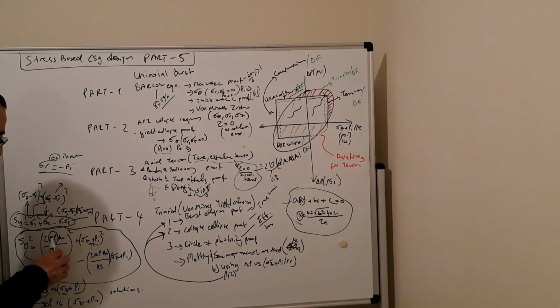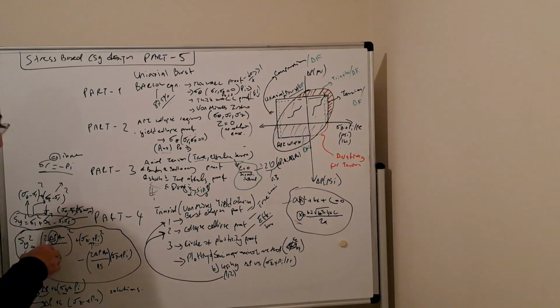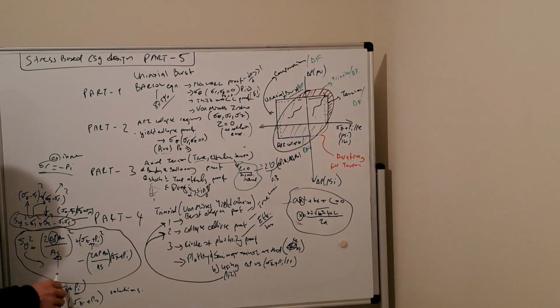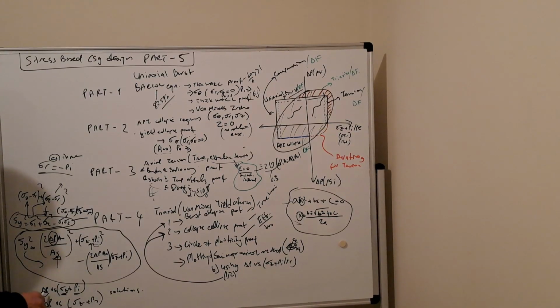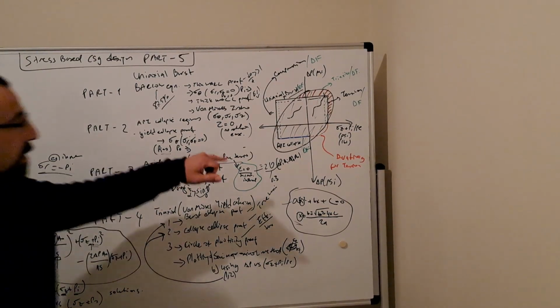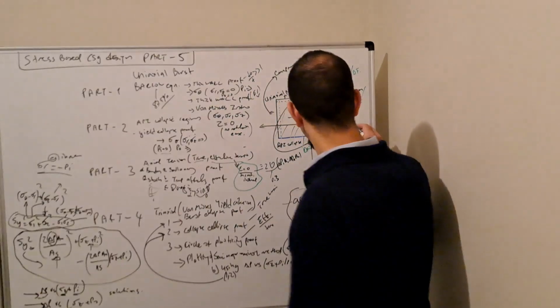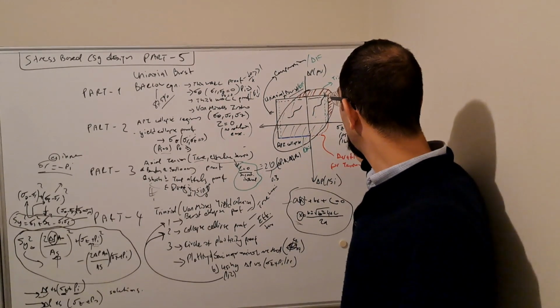If you remember, we expanded this equation, solved for delta p, and found delta p versus axial stress plus the internal pressure, right? And this was the collapse side, which is this part, okay? And the backup pressure was the internal pressure.